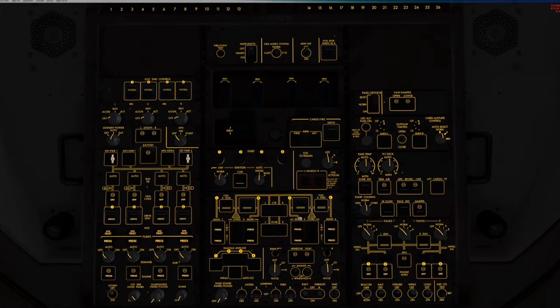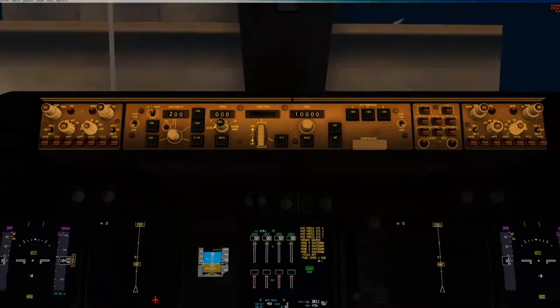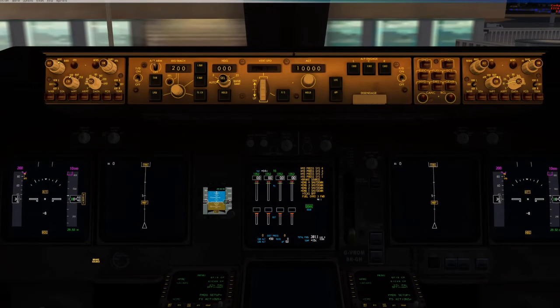We go back upstairs. Now we'll go ahead and turn the inner switch, which is the smaller switch. The little inner switch, we'll rotate that. That controls the floodlight. So as we continue to turn it, we'll go full brightness on it. And then if we go down to the Glareshield, we'll notice now that the floodlights are on, as well as the background lights. And you can see, we can see it very well now. In addition to the panel lights, you've got floodlights on now.